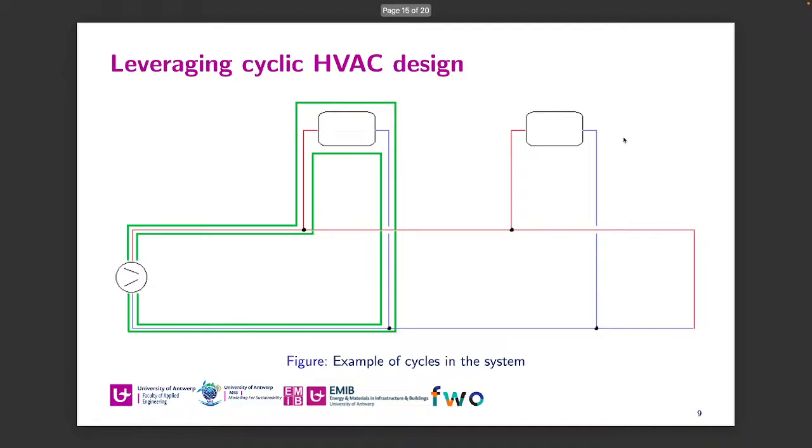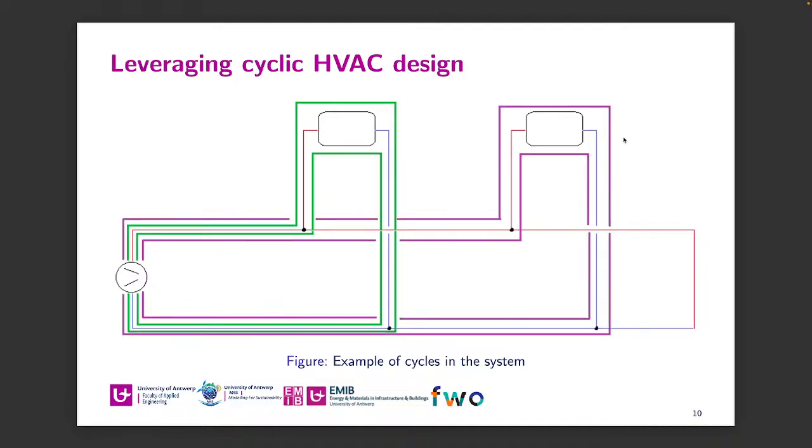As said, we divided the system into cycles. And we did this to solve the first problem, which makes shifting the water through the system hard, namely the splits and the mergers. Because you have to keep track of where the fluid is splitting into different pipes and where it is merging. And what we did was we looked at all the cycles, and then we simply shift the water through each cycle separately, and then again add all the effects back into the system, the same way as we did with the mass flows in the beginning.